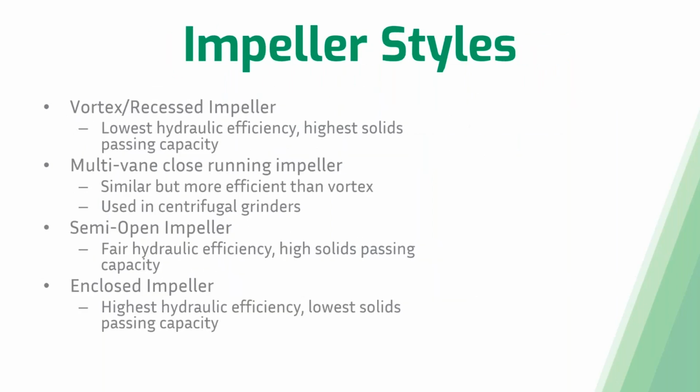So now let's talk impeller styles. Before we get into each type of impeller, one thing to keep in mind is that the more contact an impeller has with the water inside of that pump, the more efficient that impeller is going to be. On the other hand, the more contact you have with that water, the less solids passing capacity that pump is going to have in that application.